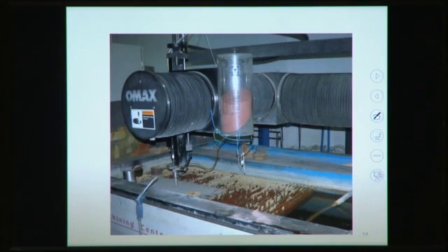This is another view of this abrasive water jet machine. This is the abrasive chamber here, and this is the nozzle. You can clearly see the nozzle, and this is the workpiece. This workpiece is kept over this table. It is properly fixed here. This is the water chamber, and the abrasives through this pipe are mixed into this mixing chamber. Then this abrasive water jet comes through this nozzle with a very high velocity, and it does the machining action on the workpiece surface here.